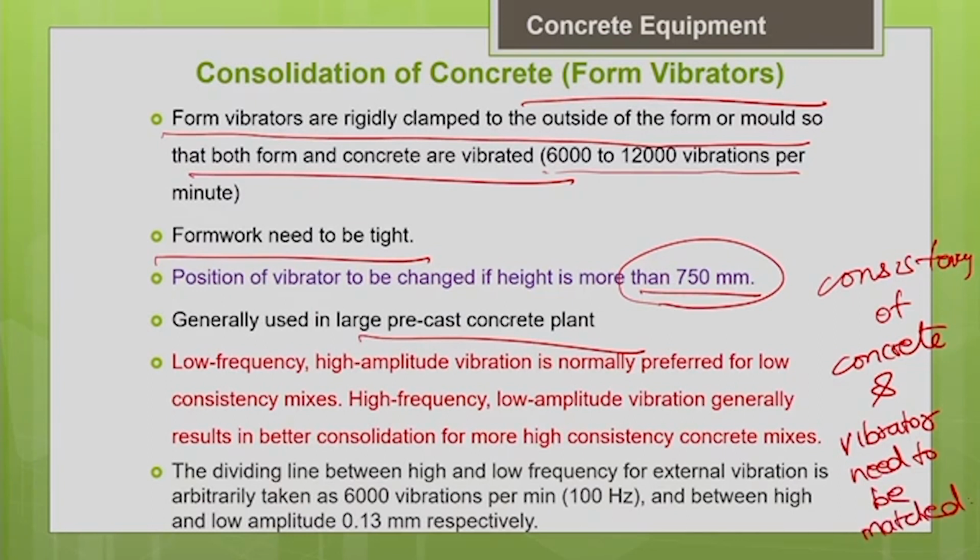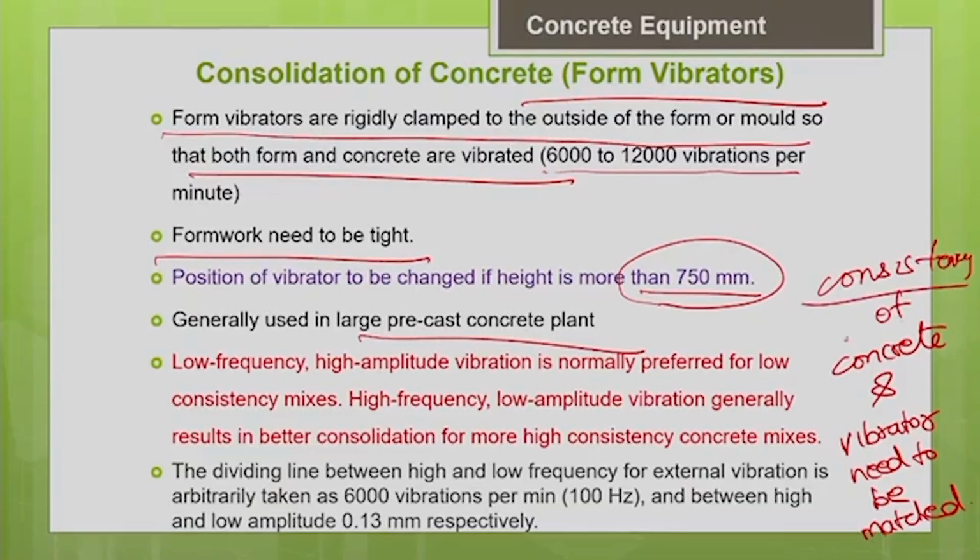Say if your concrete is very stiff, it is going to be a very dry mix. In this case the amount of consolidation effort needed is more when compared to a mix with high consistency. For a flowing concrete the amount of consolidation effort needed is less. So, the amount of consolidation effort needed depends upon the consistency of the concrete. So, the consistency of the concrete and the vibrator we have to match.